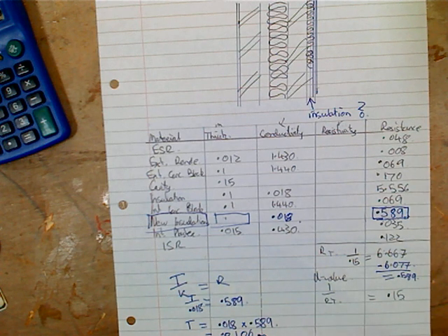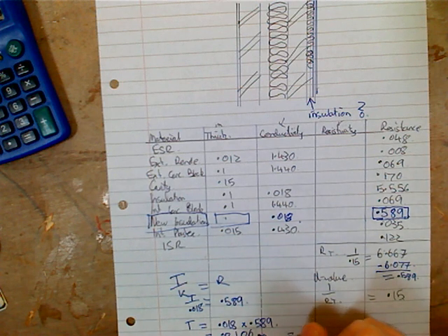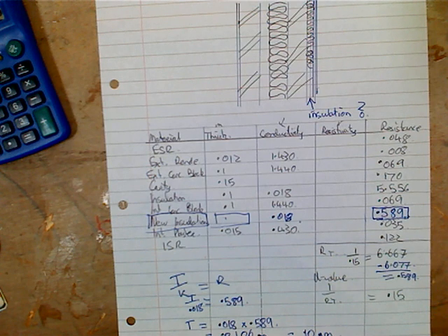What was at the top of the question, what were the measurements given to us in? It was given to us in millimeters, so I'm going to convert that to millimeters. And what's 0.01 converted into millimeters? What is it? Not 100? 10. So that's equal to 10 millimeters. That's all we need. Any more than that, no worries, any more than that is going to give us a value that is better or lower than 0.15. So if I added more insulation to that, it's going to give us a better value.